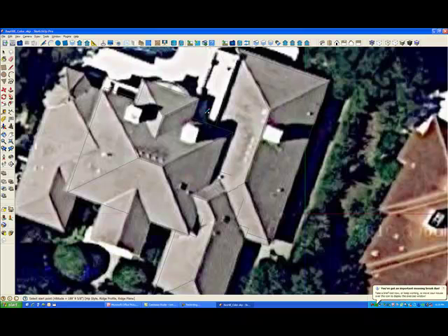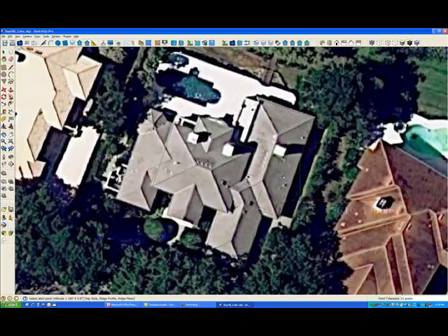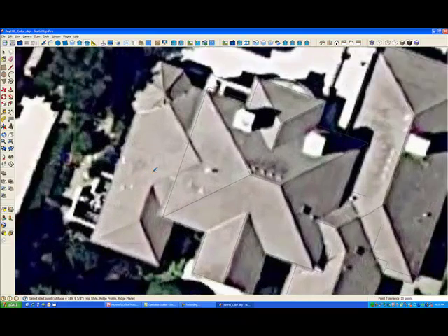So next we'll switch to the gable roof style, because this part of the roof has a flat end. Do the same technique of identifying the ridge line, getting the inferencing that tells us when it's perpendicular, lining up the eave in the image. Then we'll switch back to the hip, and over here we have a very small section of a hip roof. So we'll digitize from there, and construct that part of the roof, and then finally this section here. In this case our inferencing tells us when the eaves match.